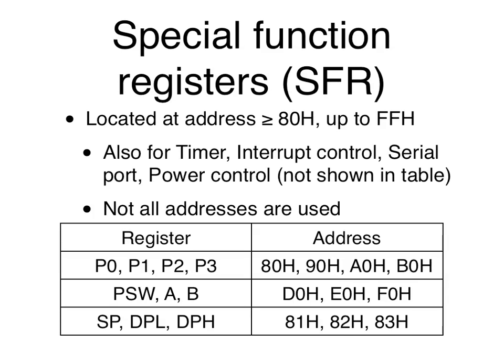Okay, so there are many possible addresses in the special function register space that are not defined by the original Intel, but later other manufacturers, as they add more things, they add a radio, they add an encryption chip, they add anything you want, right, on chip, then they assign an address to that unit, or possibly more addresses to control each unit.